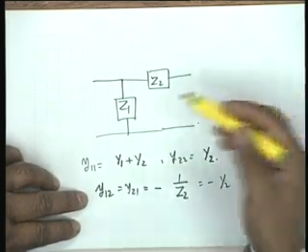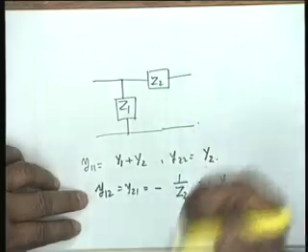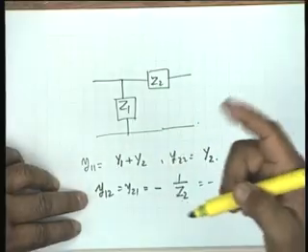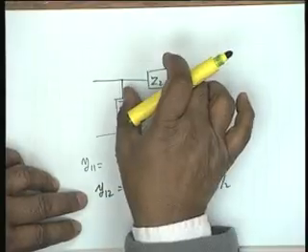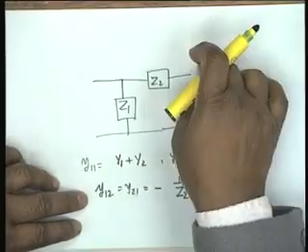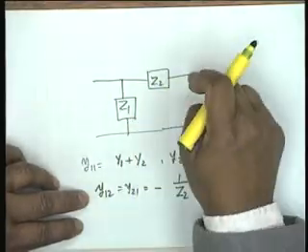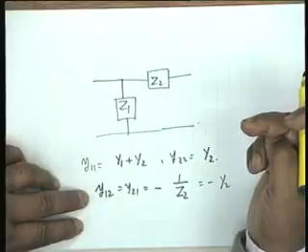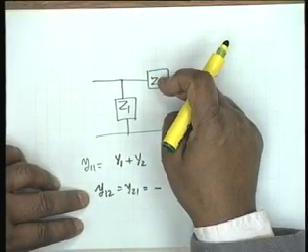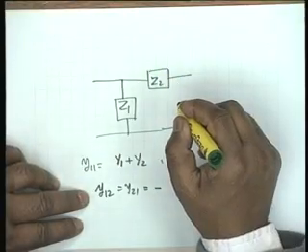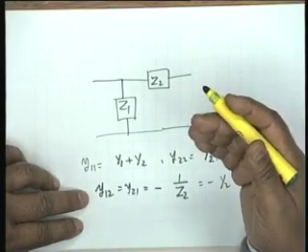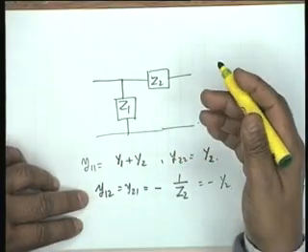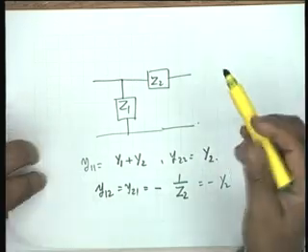You can calculate, you can also remember the pi equivalent circuit, that the bridging element between input and output, that is minus y12, and therefore minus y12 would be 1 by z2. So y12 is minus 1 by z2. Agreed? If you remember these ways of looking into a 3-terminal network, you see things will be very easy in future.